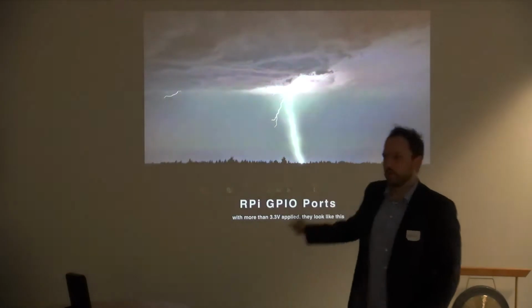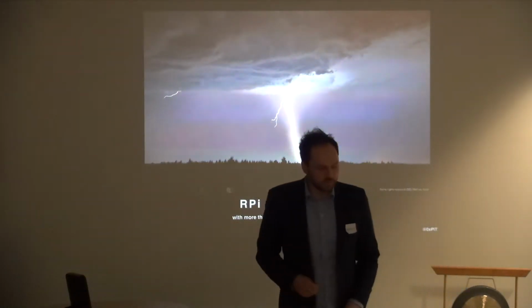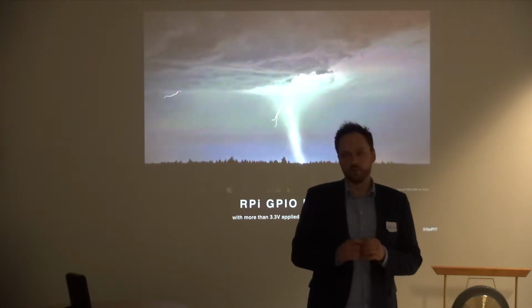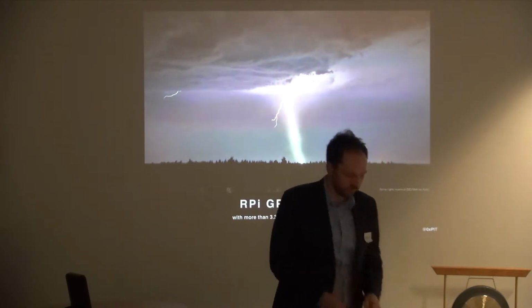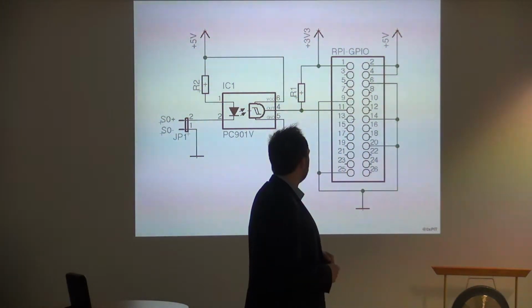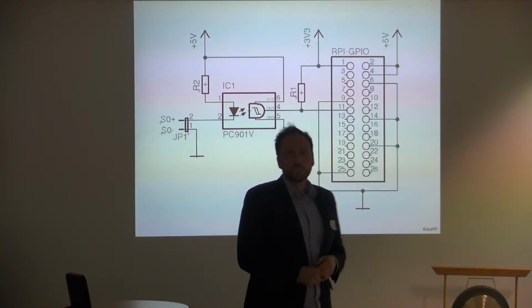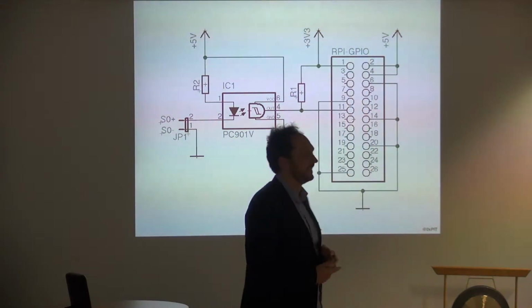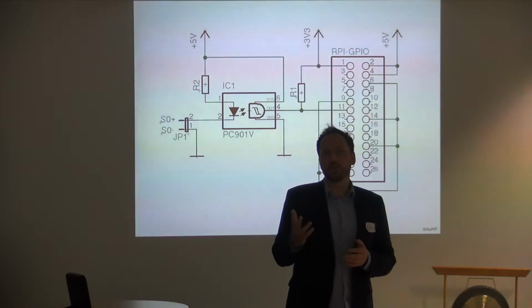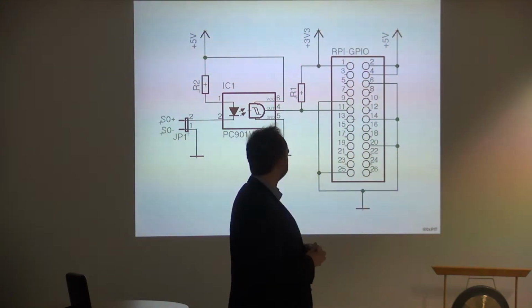And, as this is a lightning talk, be warned that a Raspberry Pi GPIO port takes 3.3 volts and no more. Otherwise, it will actually explode. You tried that, didn't you? Yeah, several times. I think from the 18 GPIOs, there are 4 left that work.